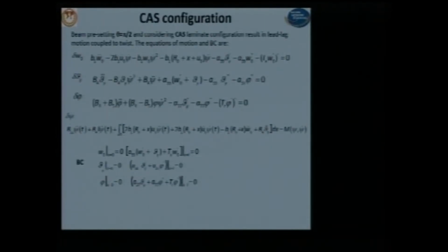And finally, we get to this reduced model. We take into account only three equations. It means bending, twisting, and rotation of the cross-section due to the Timoshenko effect. And we have this driving equation, which is related to hub motion. And everything is coupled, and there are boundary conditions. And now we have to reduce the problem from partial to ordinary differential equations.